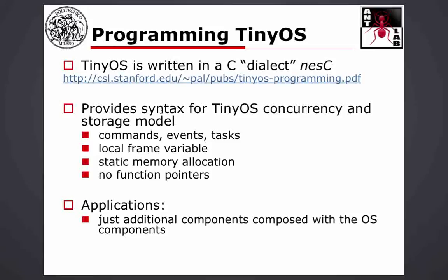You also have some constraints in terms of variables that you can use. You cannot use, let's say, floating point variables. Or at least you can use them, but you have no hardware support for floating point operations, so you have to be very, very careful when you do them. Also, since your processing power is limited, you have constraints on the type of operation that you want to do.